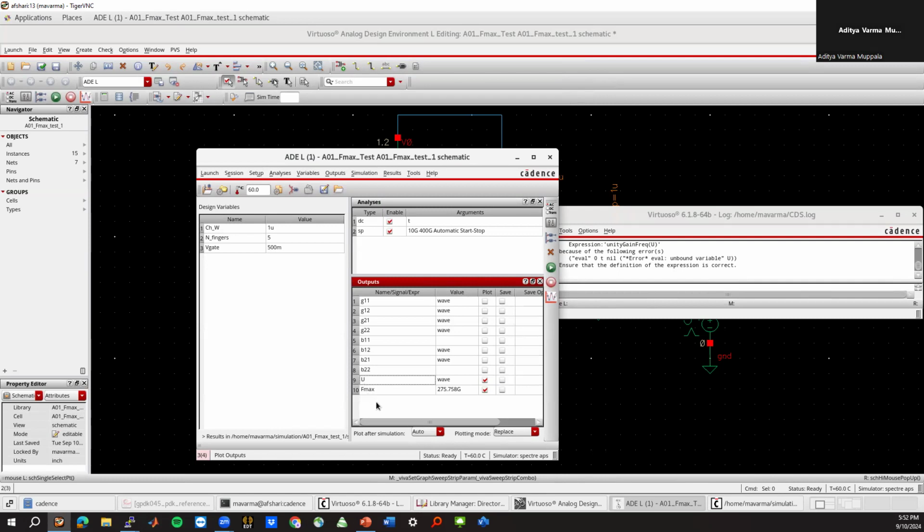Okay, so essentially here we've covered what is a PDK, how to set up a PDK. In this case, the generic PDK, but other PDKs can be more complicated. You may need to talk to someone who is sort of an expert in your department, or an IT person who handles this area of setting up PDKs. So once you have it set up, go through all the documentation very carefully, take notes of things like what is the maximum current handling capacity of different metal layers, what is the maximum voltage swing that is allowed between the drain and gate, or the drain and source, or the gate and source. That will stress the transistor, so those things will be mentioned. That's also very important to keep in mind.